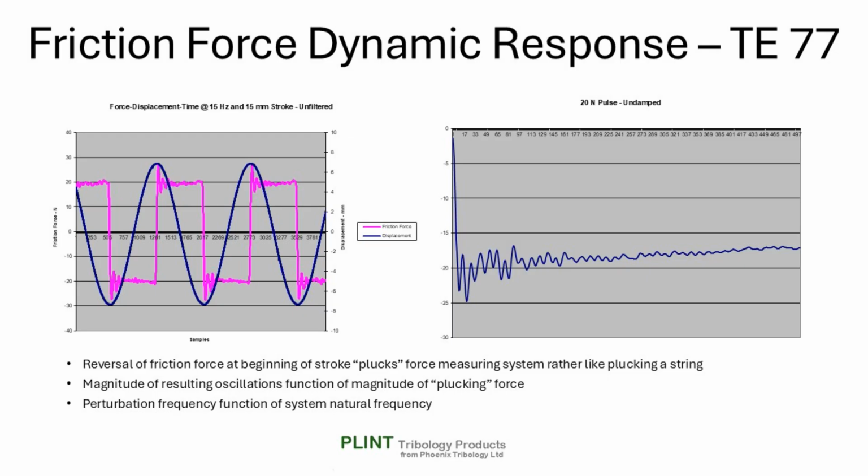The signal perturbation cannot be anything other than a resonant harmonic force giving rise to oscillation. The reversal of the friction at the beginning of the stroke effectively plucks the force measuring system, rather like plucking a string. The magnitude of the resulting oscillations is of course a function of the magnitude of the plucking force.